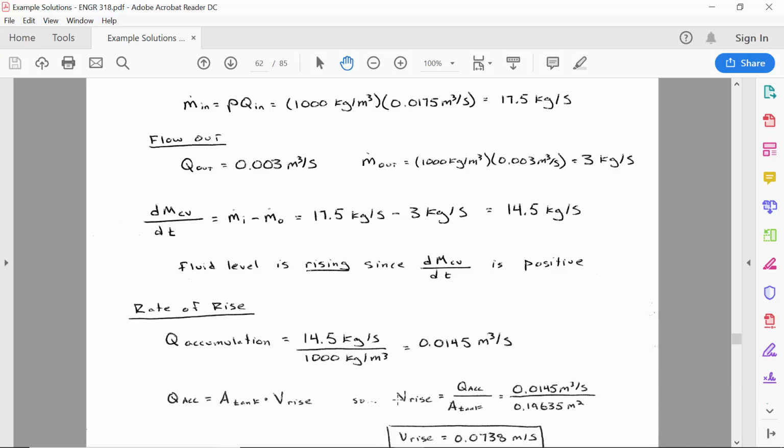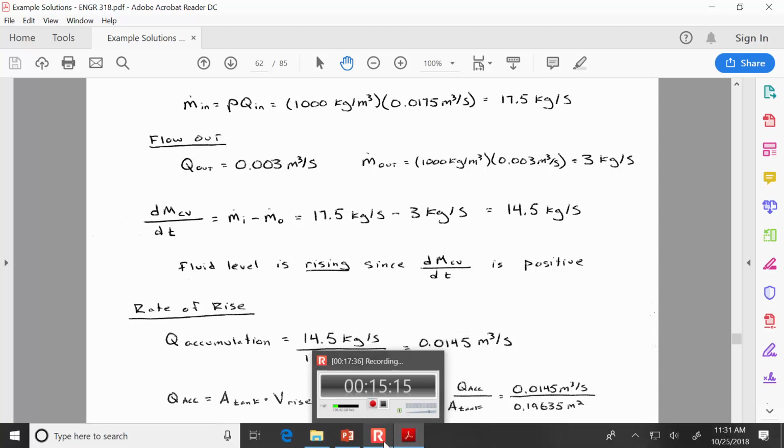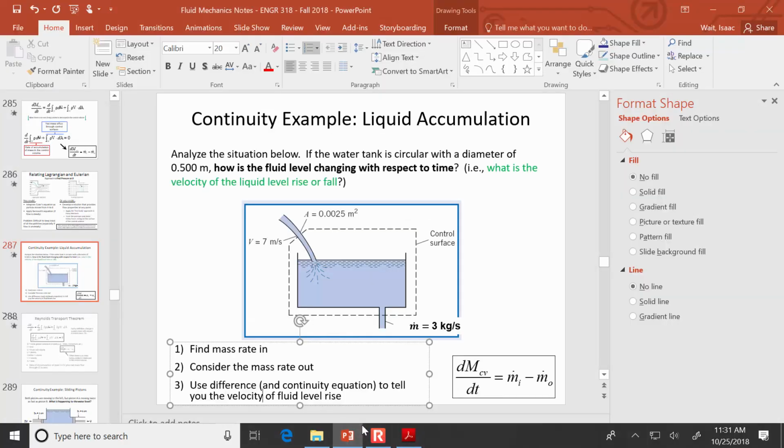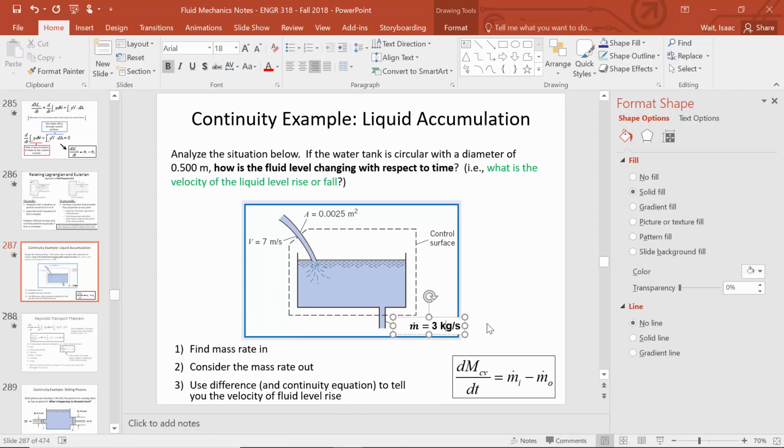Yes? So when I did it, I didn't convert the flow rates to mass. And that's fine. I asked you to convert it to a mass basis just to reinforce in your mind that m dot is Q times density. But you're right, you don't have to solve this on a mass basis. You could have just gone volumetric. So you may notice that I just changed the example so that in future semesters they'll be forced to do the mass flow rate and not feel like they wasted their time. But anyways, good point. Are there other questions about this example?